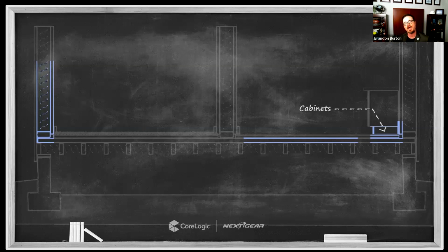And generally speaking, the higher pressure systems are going to require smaller openings to get the airflow into those spaces. The lower pressure systems are going to require larger openings, right? To the extent that we may be talking about openings that are 1 or 2 inches in diameter for really low pressure systems. Those would be things like taking your general carpet dryer and using an adapter on that with vents, right? Those are really low pressure systems with good airflow, but really big openings are required to get that air to move into those spaces. All the way through to systems that are producing 100 inches of static pressure or more that are capable of delivering air through holes that are a fraction of an inch.